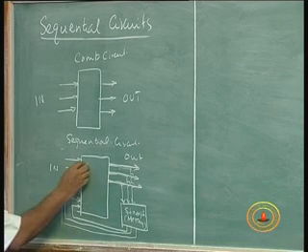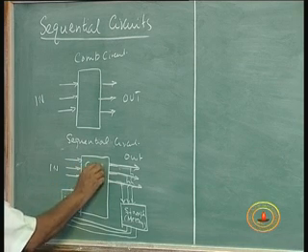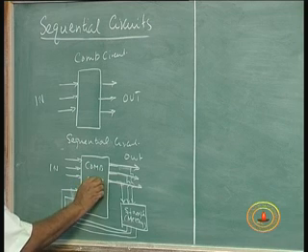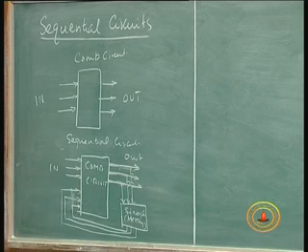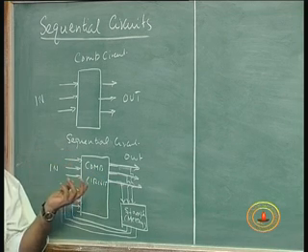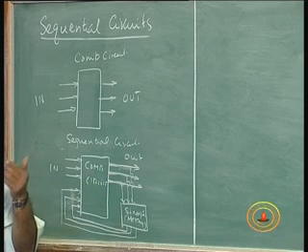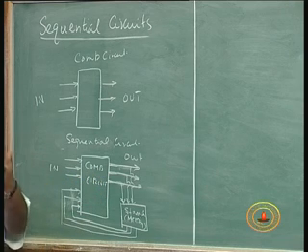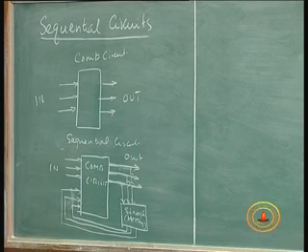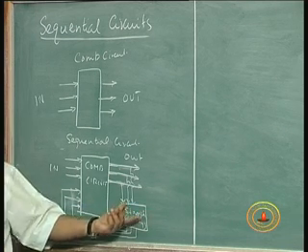So, this is still a combinational circuit, which means there is nothing much here for us to do, because we already know how to design it. Given an input, you do the truth table, Karnaugh map, simplify, get the implementation using whatever type of gates you are asked to use, and then we have the outputs. But in between we need to have these elements for storage.